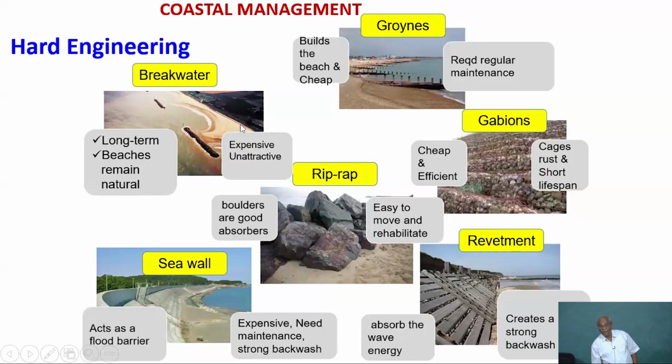Because of this, the lee side of the breakwater, in between the breakwater and the shoreline, will become a shadow area, wherein the wave heights will be less compared to the adjoining area. So the sand will come and deposit in between the breakwater and the shoreline, and thus the shoreline will tend to advance towards the breakwater.